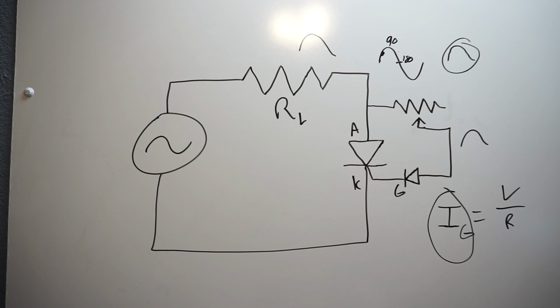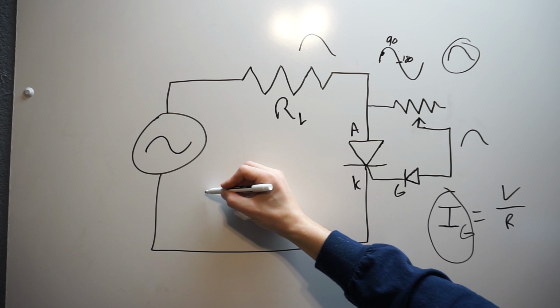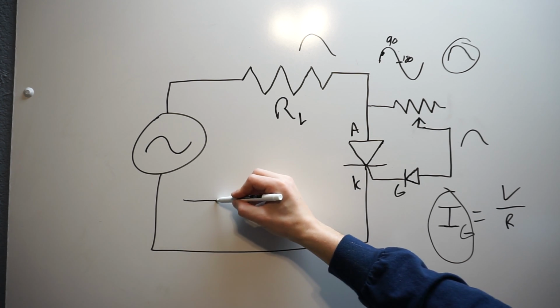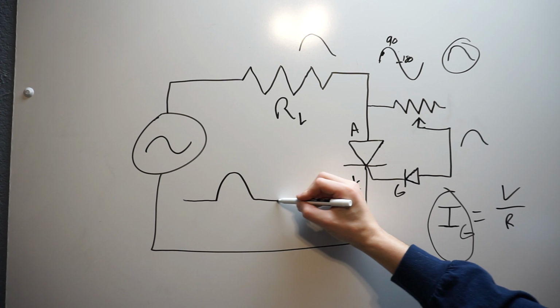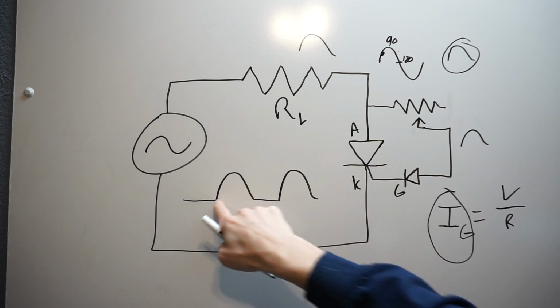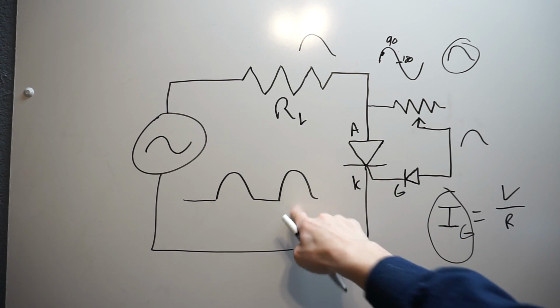And that gets into what we call phase control. Again, I don't want to go into great depth here because that's not what we're talking about, but it's such a major use for these that I had to explain. We'll actually look at that on the oscilloscope, I'll show it to you. On our output waveform of this SCR, if it was just fully latched, it would look like this, and you would have your positive half of your waves making it through as long as it was latched.